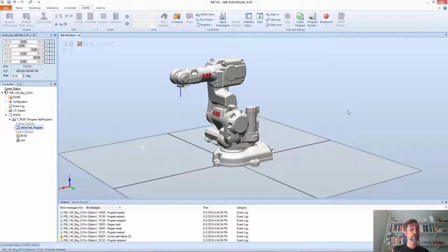There are many different ways we can do this, and it depends very heavily on which brand of robot you're using. But in this video, I'm going to showcase this for ABB robots. The really nice thing about RobotStudio in particular is that when you create a virtual robot like the one we are seeing on the screen right now, you can use it for loading programs offline, but also this robot in the simulation is behaving literally as if there was a virtual robot connected to my local network in my computer right now.